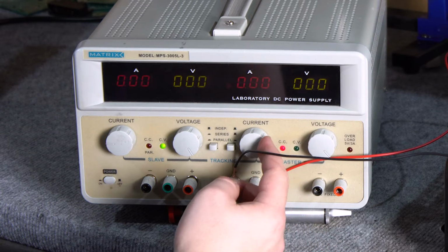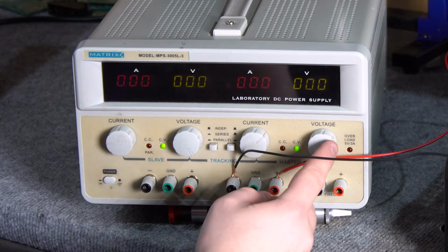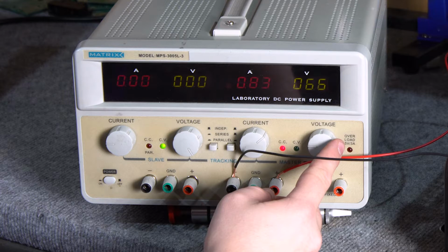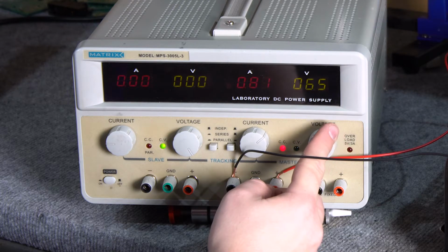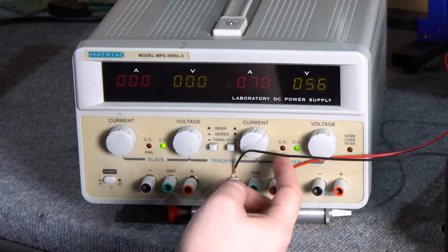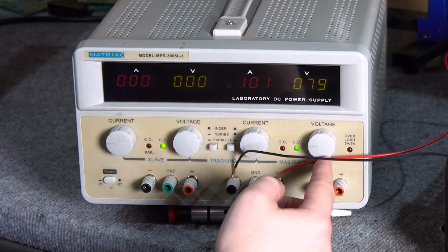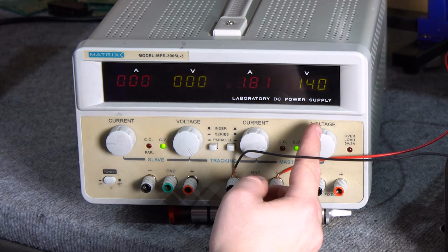Let us consider a situation where our system should be powered from 15 volts. We do not know if it's operational. If we did not set a limit and a short circuit occurred, for example, in the power section of our system, we would allow a significant current to flow through it, which could damage functional components or paths on the PCB.